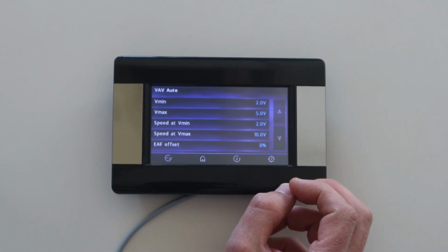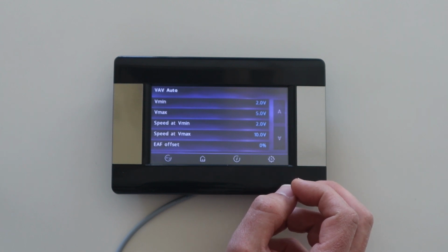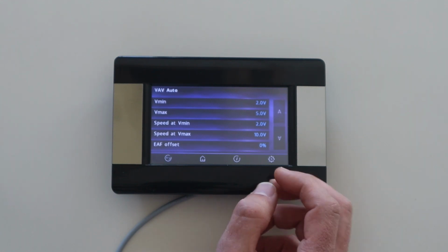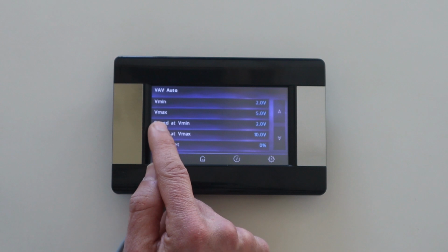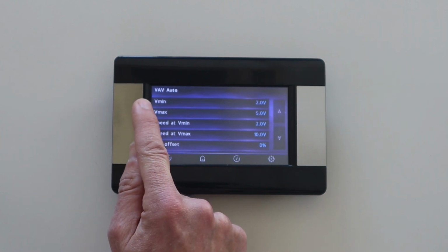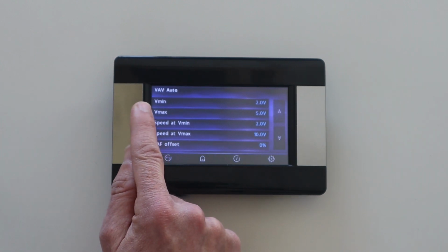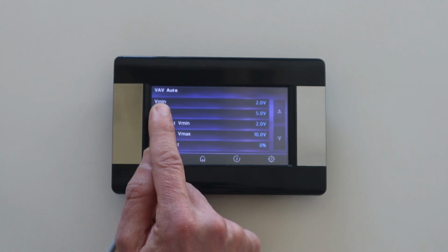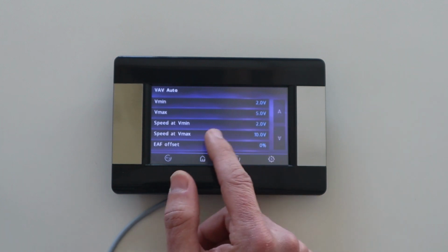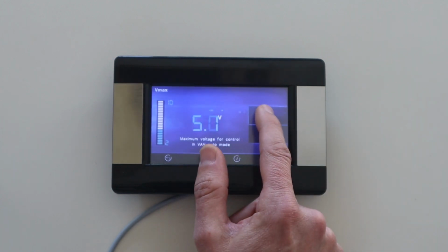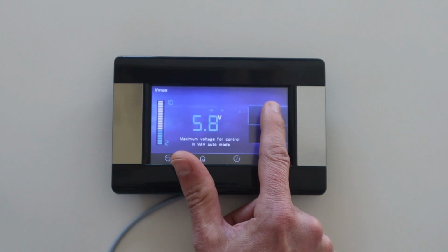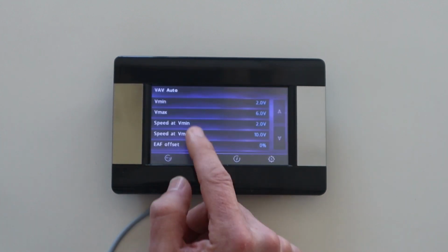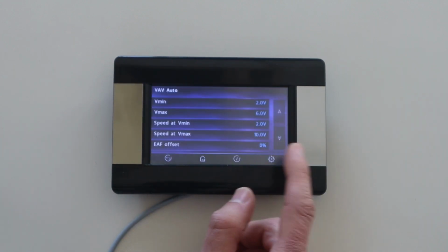We have seen before in a presentation that in this case it's necessary to configure a ramp defining the minimum speed and maximum speed here, and the input from the sensor, external sensor, to establish the proportional ramp. So there are the 4 points. If we want to modify the settings, it's that simple. So only access this button and change the value as we want.